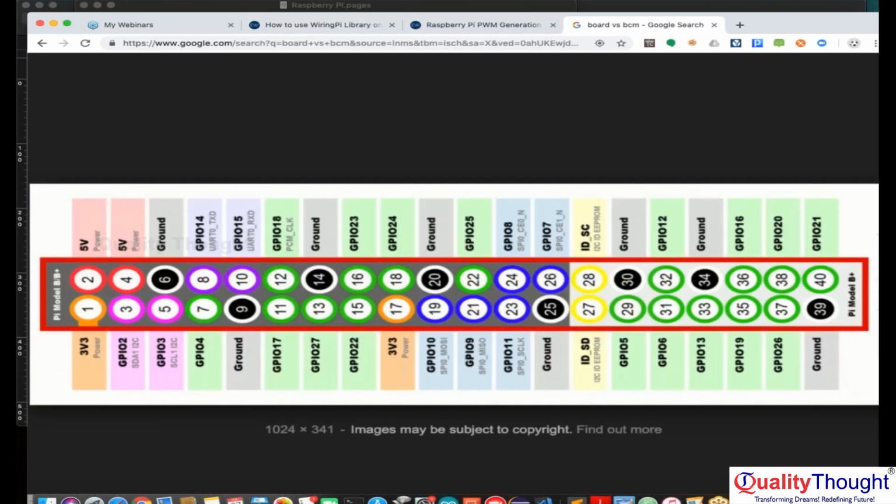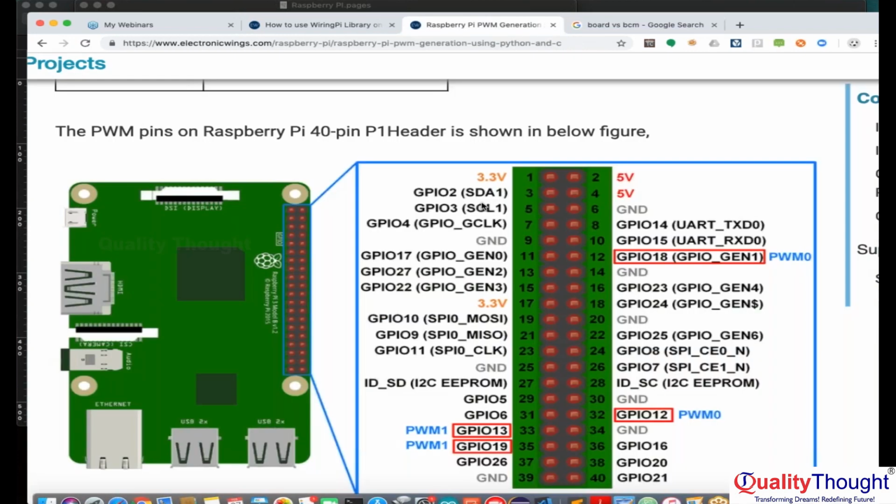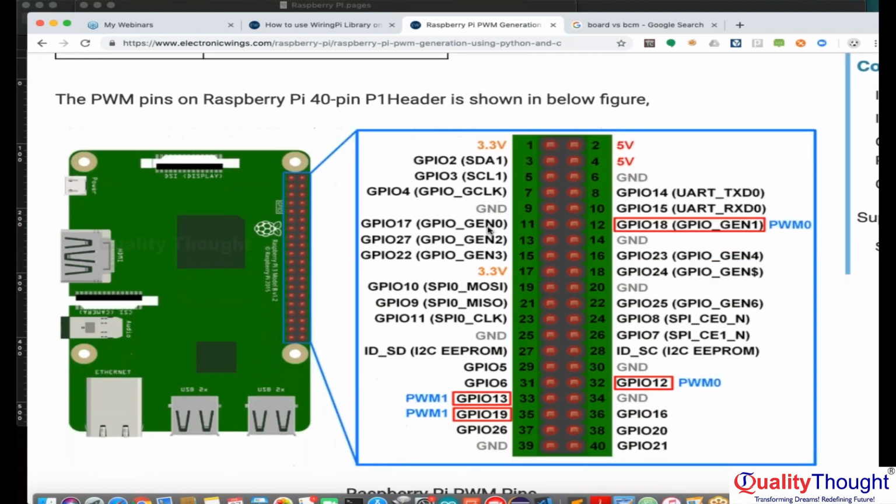So you can use it for any purpose. So see, for example, here is the case. What he is trying to say is that there are multiple operations on a given pin. Here it can be used as a PWM pin as well as a general purpose pin. Multiple purposes. So here, can't I use 14 and 15 to control an LED? Yes, I can do that. It can act as a GPIO pin as well as an RX and TX pin.